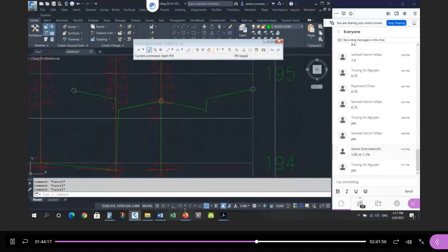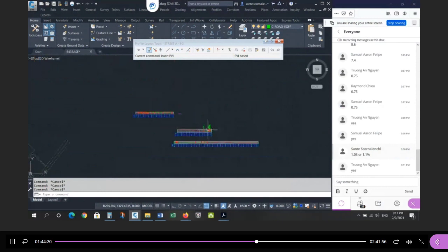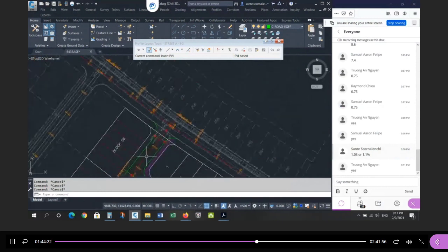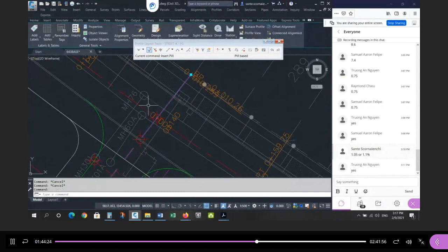Because the two roads do not meet at 90 degrees. So if you look at the plan view, right, the angle between this line and this line is not exactly 90 degrees. So I'm not looking at a line that's a cross section of Ledger Way. I'm looking at a section that's not at 90 degrees to the center line of Ledger Way. So it's going to be very close to 2%, but it's not going to be exactly 2%.